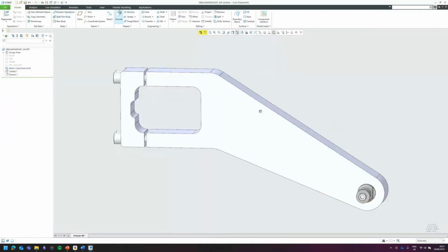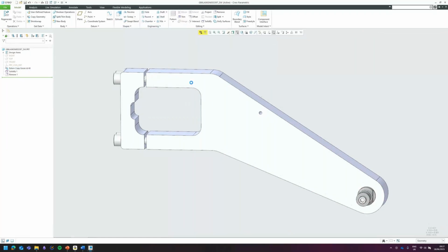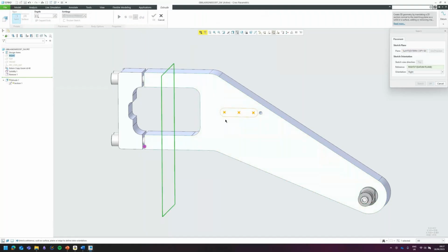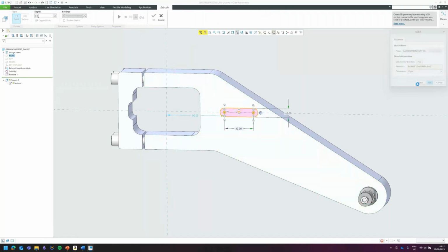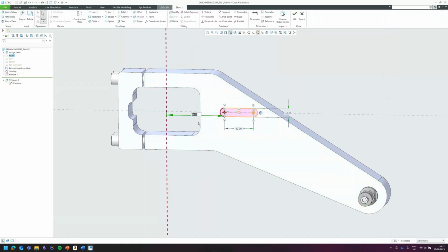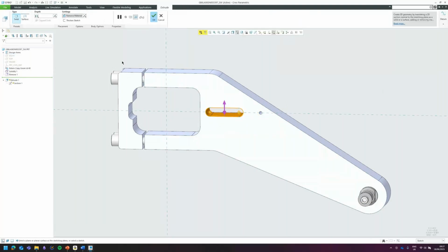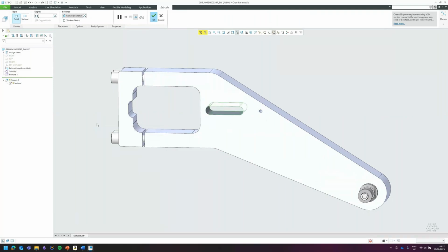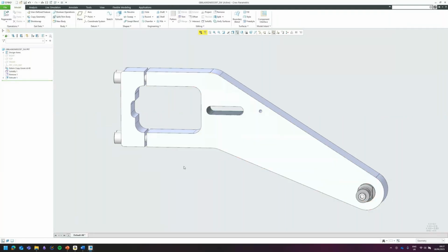And I like to go through the right-hand mouse button on the feature itself, hop in the rectangle, choose my sketch plane. Maybe I want to modify some of the dimensions, so I'll hop into the sketch. Click OK. It's saved my settings and we're good to go. Okay. So these feature presets, I think, are a really, really handy addition and can really speed up your workflows.